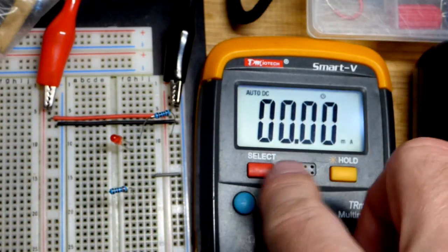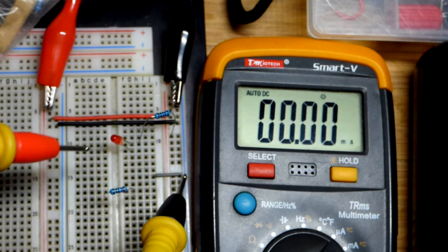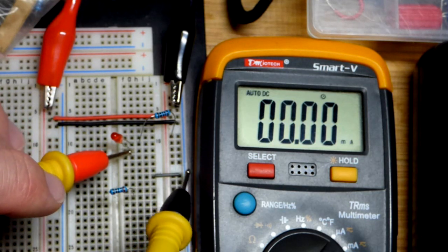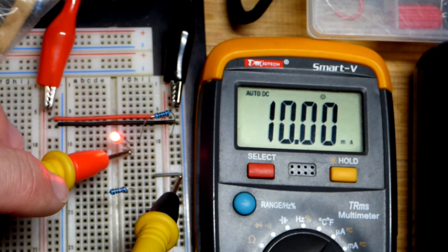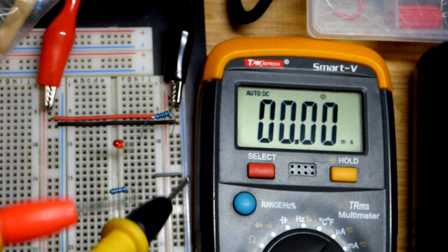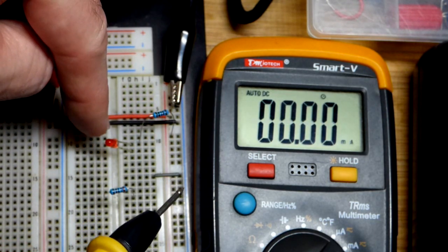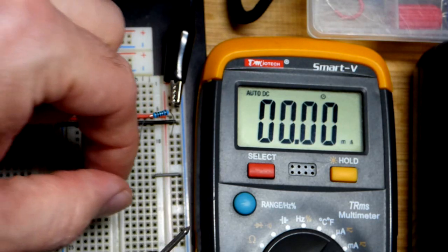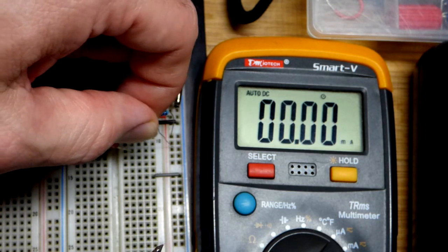I think this goes up to 600 milliamps, this particular unit. And when it gets dark enough, the backlight turns on. So we have to complete the circuit, going to the short lead, the cathode, and then the negative supply there. There you can see we got pretty much 10 milliamps of current. Right there it's saying spot on, 10 milliamps of current. And so that was the 12 volts, but the LED is dropping 2 volts, divided by 1,000 ohms is about 10 milliamps of current.